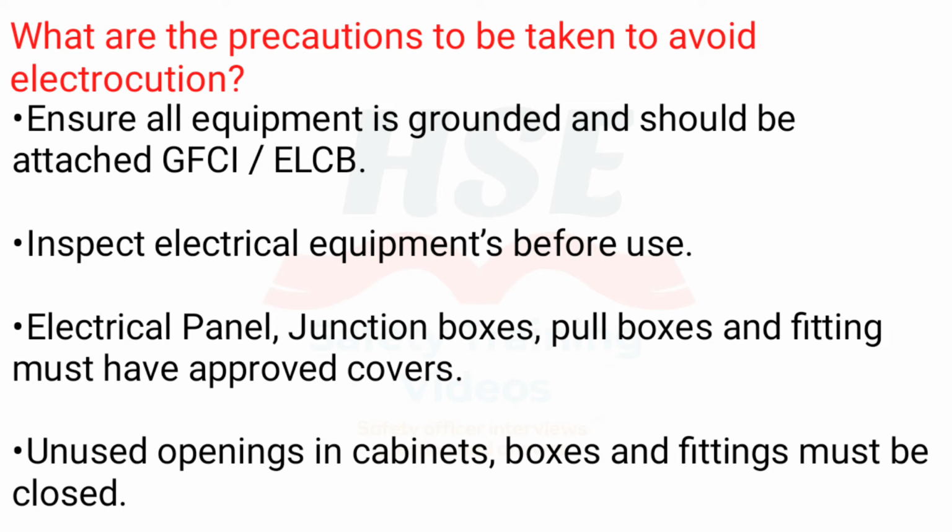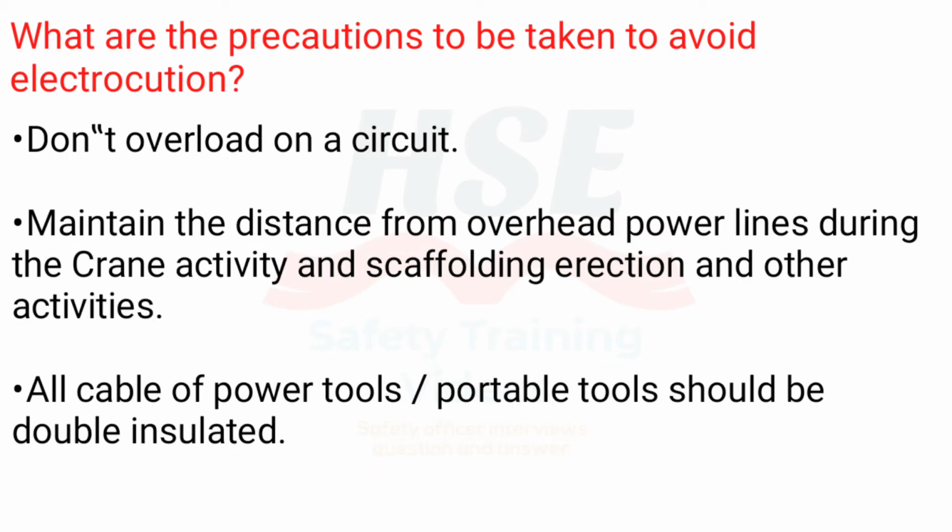Electrical panel, junction boxes, pull boxes and fitting must have approved covers. Unused openings in cabinets, boxes and fittings must be closed. Don't overload a circuit. Maintain the distance from overhead power lines during the crane activity and scaffolding erection and other activities.